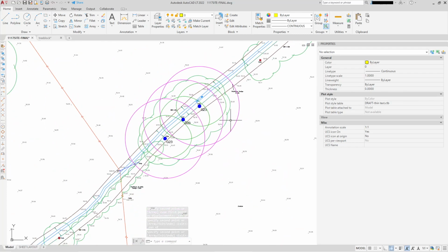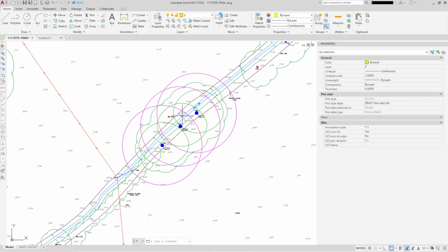There's a tree group. Now you may want to merge these canopies and RPAs so it's a single flowing line. To do circles, you can use polyline rather than sort of trimming all these bits away and joining them together. So I'd actually redraw the RPAs because they're circles.